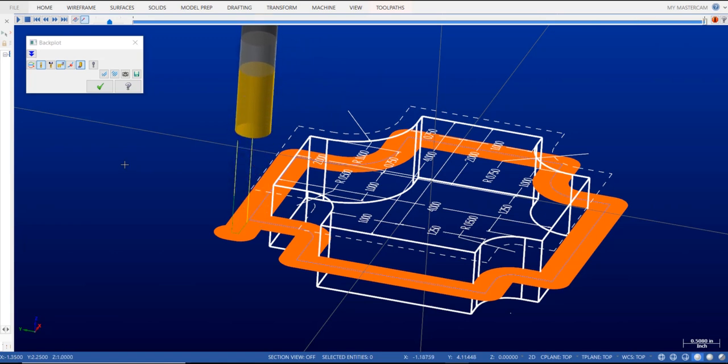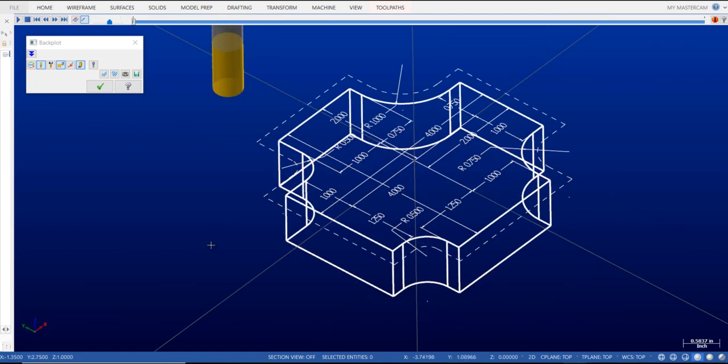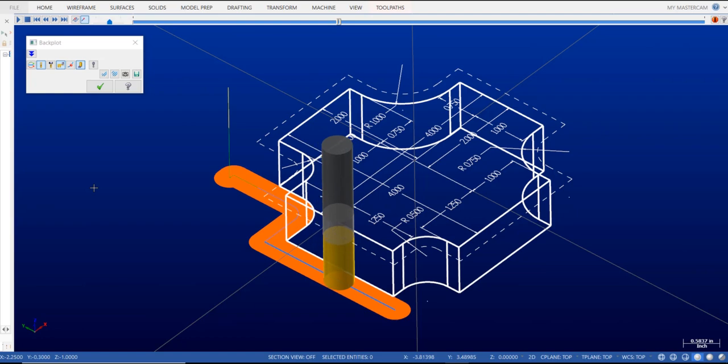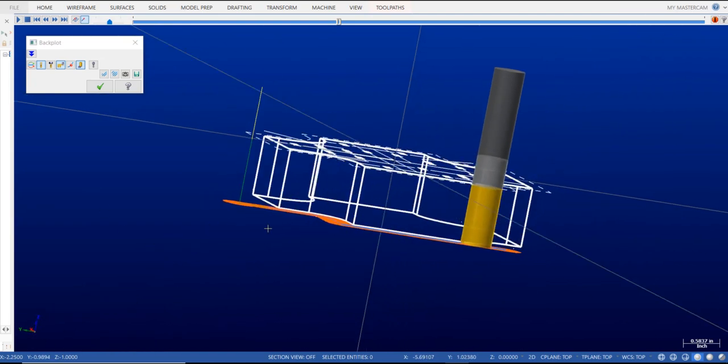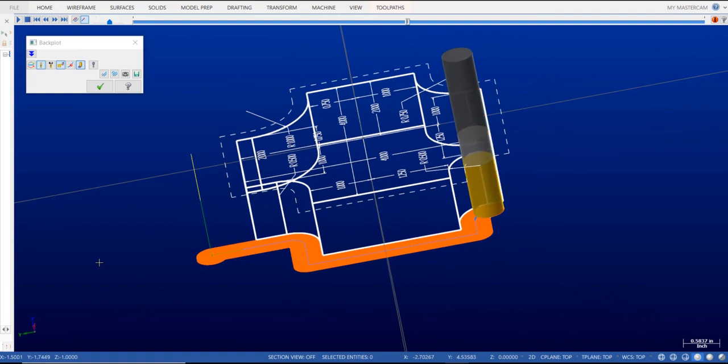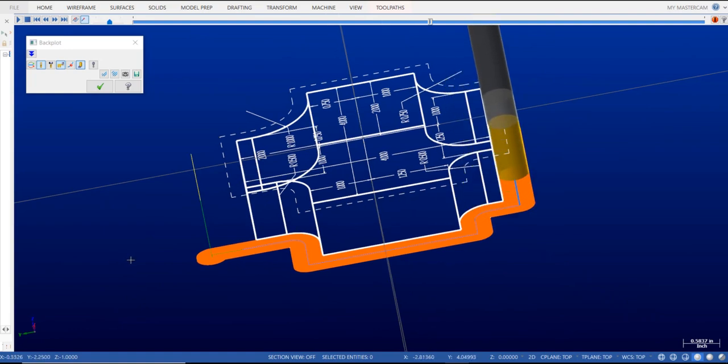Now let's take a look at a line right. So a G42 would be considered line right, and we would still have that perpendicular move to activate cutter comp. And as you can see, we're going around the part in the counterclockwise direction. And if I'm looking at the tool as it's going away from me, I am on the right side of the part.